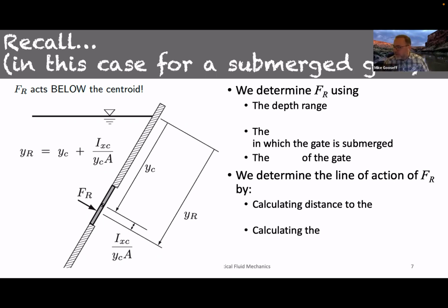But essentially, the depth range of interest. And what we mean here on the left-hand side is, we would go from this value of depth to this value of depth, right? These are H values that are related to the surface of the interface of the fluid with the atmosphere. And below that free surface, we know that pressure increases linearly with respect to the specific weight.